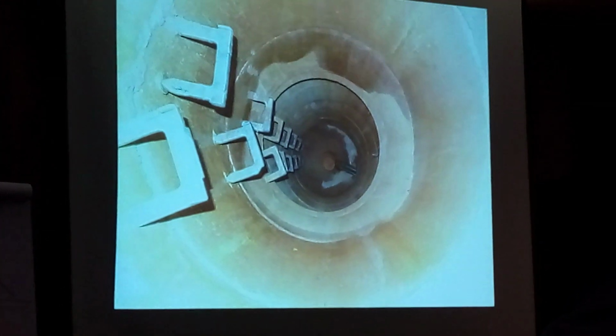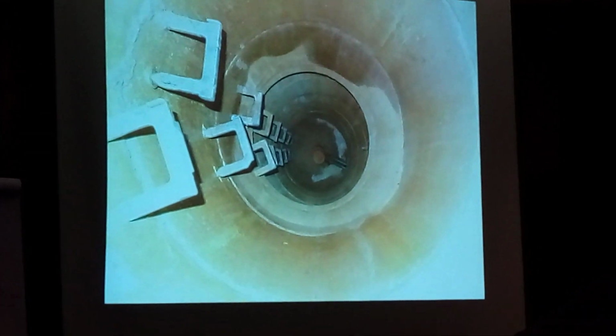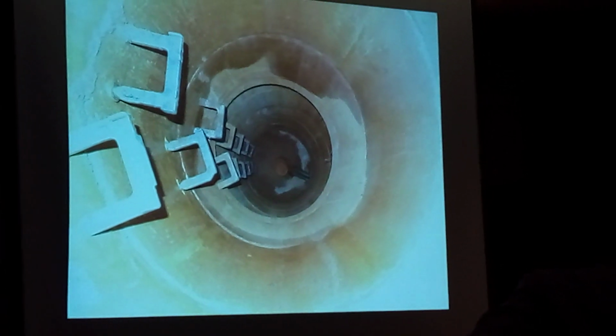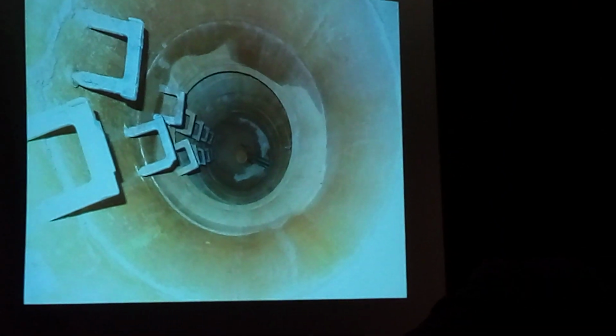The other thing, this is a manhole, and you're supposed to climb down there, and if there's seepage, go and take a reading there. I can't fit in that manhole. I can't climb down there. So if you're doing designs, think about the persons. I'm taller than most people, but even an average sized person struggles to climb down there. So think about access to your monitoring points. Make it easy for the guys. If you make it difficult, you will not get good monitoring results.